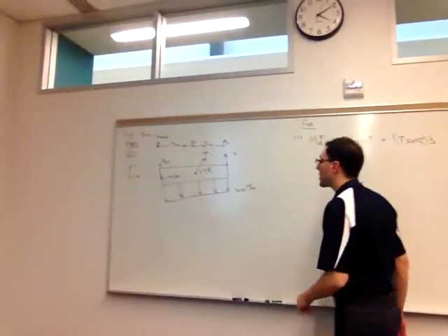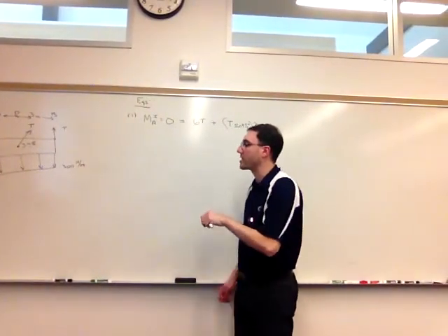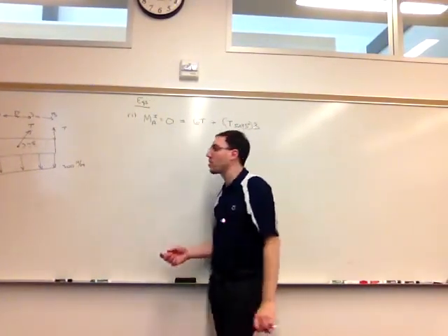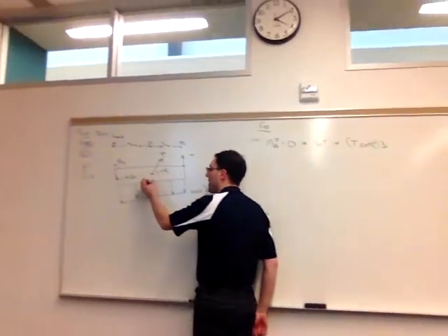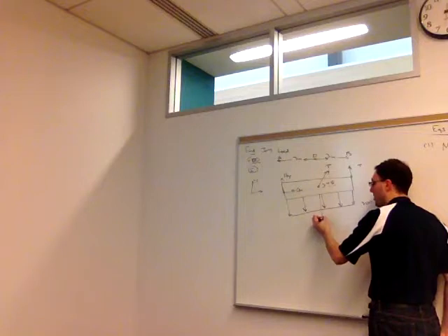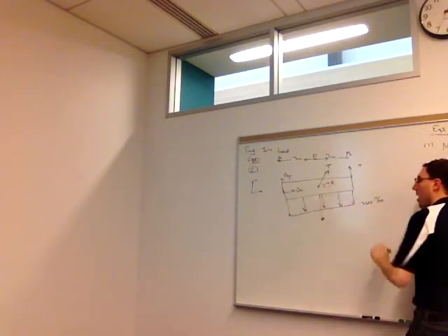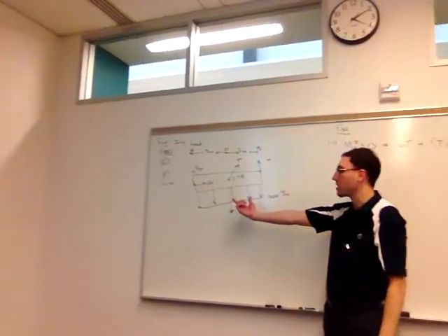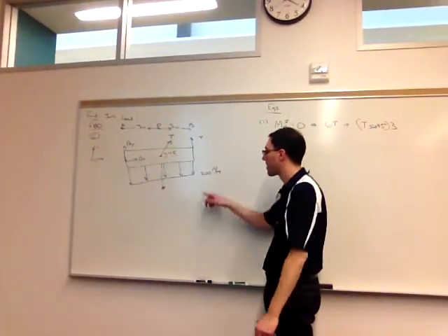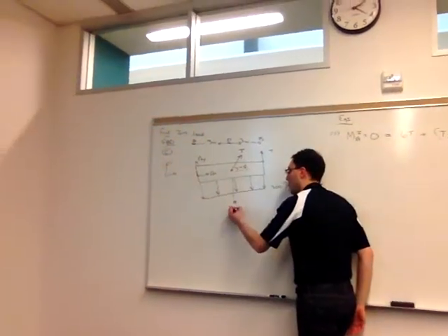And then what will the moment caused by the distributed load be? Right, 1800 times 3, so that comes at this step. This is where you can simplify it. So remember, we can simplify this externally, which is what we're doing now, to one point load that acts at the center of the distributed load, since it's a rectangularly distributed load. So its intensity times 6 is 1800 newtons.